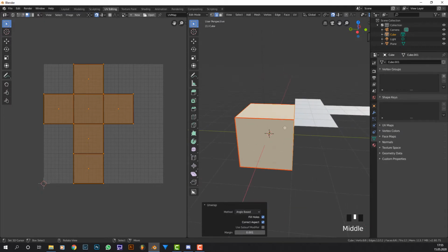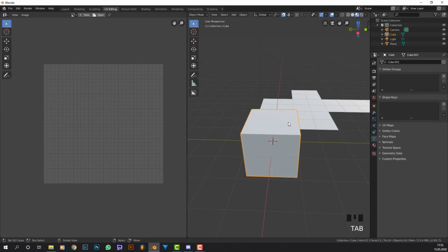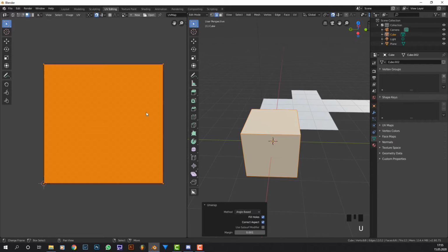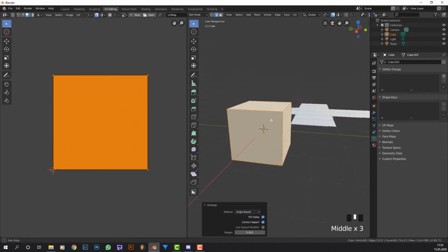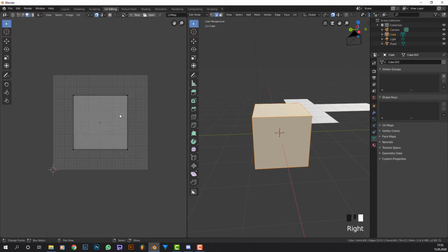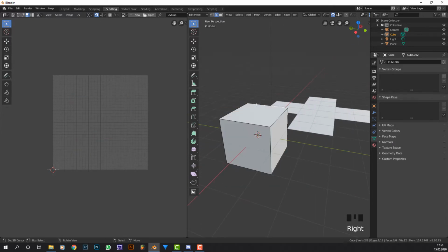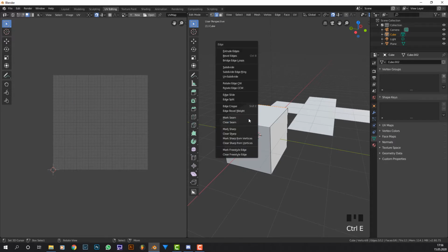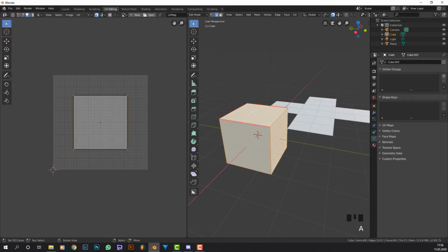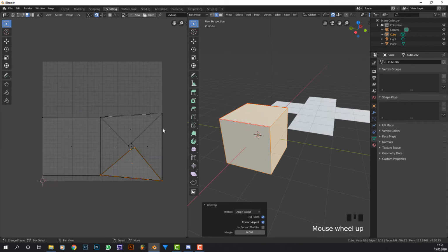So what would it look like if I didn't have any seams? So I'm gonna clear the seams, then unwrap it again, and because we have actually had a result before, it shows the same result. So if I add in another cube without UVs and just press U, unwrap, it shows you this. This is a cube projection. This is the exact same result we would get by hitting U and cube projection, and that's not what we want. What if you were to place in some loop cut, some seams, but not everywhere, and then hit U? You would get something that looks like this.